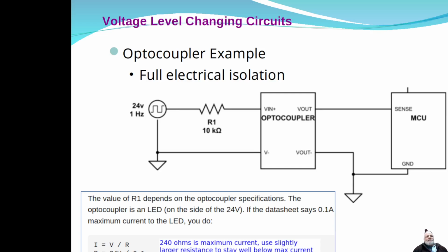So in general, if this was the maximum current to activate this thing, then you want to be below the maximum current. So I'm saying you should probably use a minimum of like a 330 ohm resistor for this particular setup, if this is the maximum current they're saying that they want.